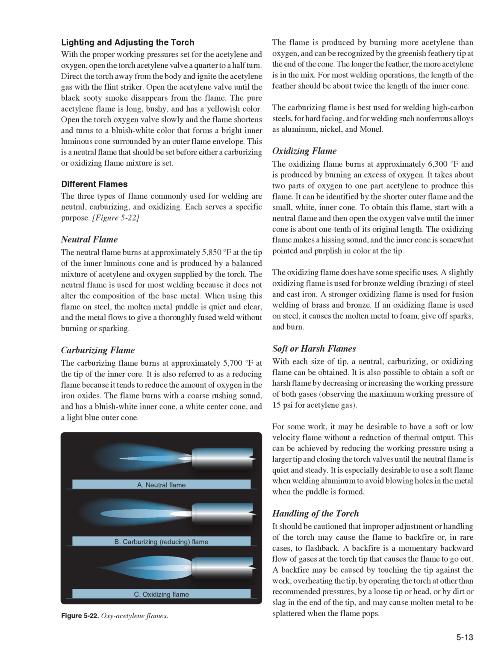Oxyacetylene cutting. Cutting ferrous metals by the oxyacetylene process is primarily the rapid burning or oxidizing of the metal in a localized area. This is a quick and inexpensive way to cut iron and steel where a finished edge is not required. Figure 523 shows an example of a cutting torch. It has the conventional oxygen and acetylene valves in the torch handle that control the flow of the two gases to the cutting head. It also has an oxygen valve below the oxygen lever on the cutting head so that a finer adjustment of the flame can be obtained.